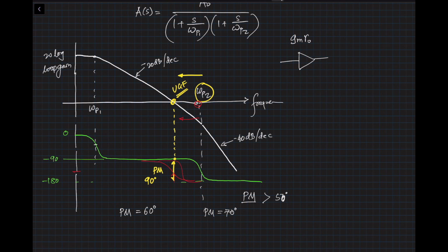Now, to get more and more gain, we like to put more gm Rout stages in cascade. Unfortunately, when we try to get more and more gain, you have multiple poles. For example, this stage will have a pole here, and the second stage will have the second pole, and these poles may not be far away from each other. As a result, just putting two gm Rout stages next to each other, you will inherit two poles which could be close to each other, which will result in an unstable system, as we just looked at.